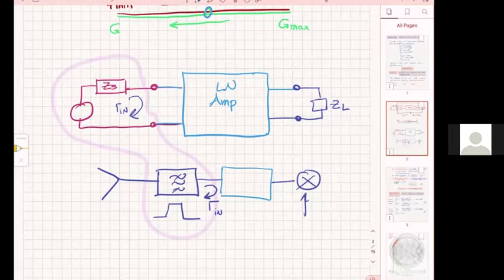That's how usually in circuits we define a low reflection coefficient. Many times, when it comes to mostly passive components or connectors and such, you're not going to see the reflection coefficient, you're going to see a VSWR. And how much is the VSWR? Do you remember? 1 plus the magnitude of gamma, divided by 1 minus the magnitude of gamma.